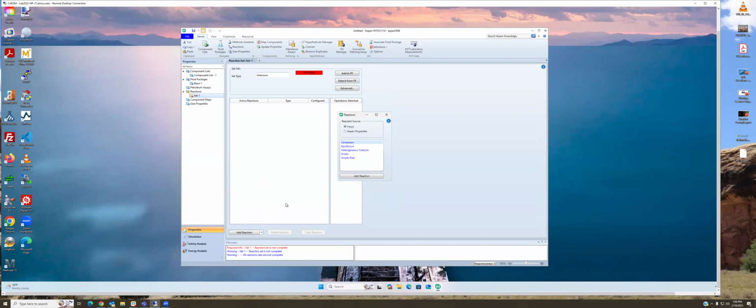Our first reactions, including the reaction that takes acetone and makes ketene, are kinetic reactions, meaning we have the kinetic parameters, the rate expression needed to model this. And so we will use kinetic reactions and kinetic reactor for this reaction, as well as the byproduct reaction associated with it.